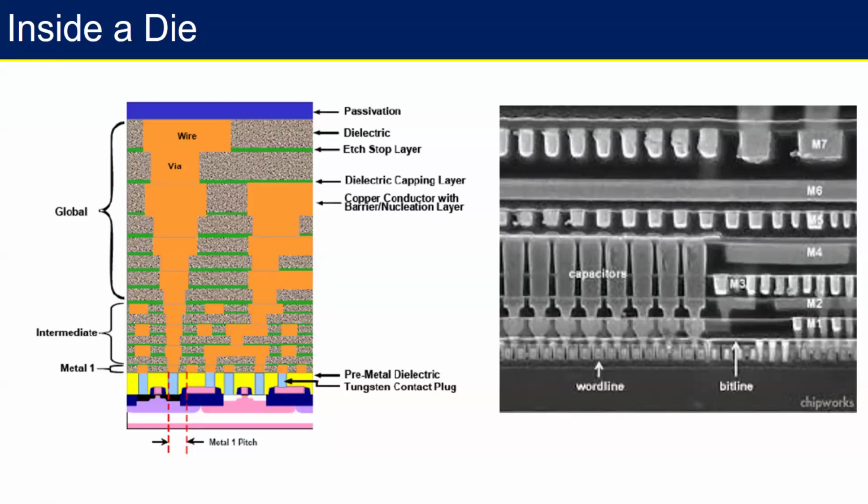And when we make a die or a chip, the substrate is typically silicon, right? That has been the workhorse of the industry for the last 50, 60 years, and it continues to be the workhorse. So that means on a silicon wafer, I then make transistors, which could be made of a silicon channel or of different channels, right? People have been trying very different channels, which we'll talk about in some other video, about what different channels people are talking about for logic transistors.